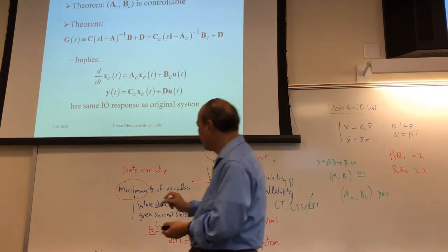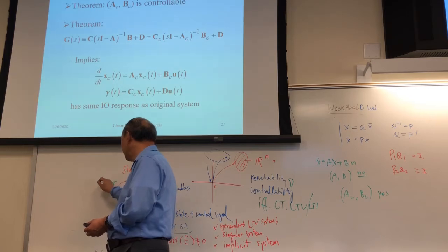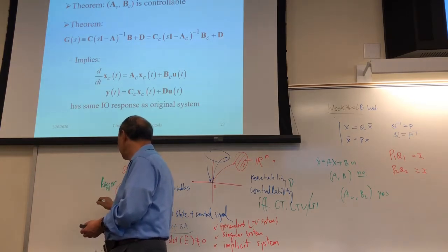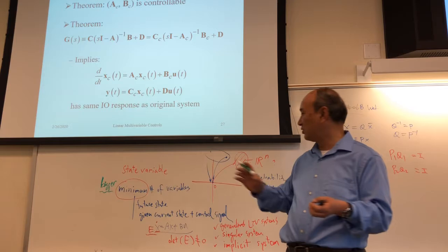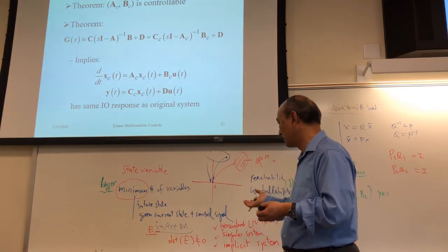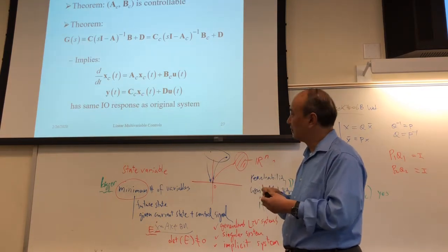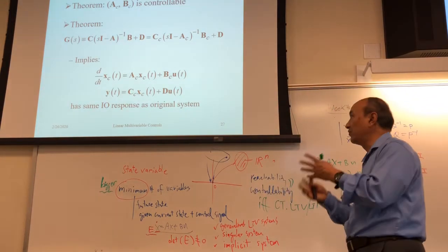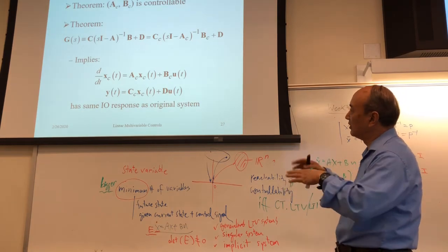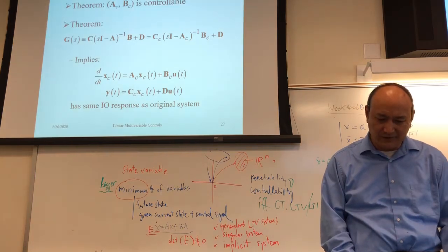While the original bigger system, the reason you had that kind of bigger system is you didn't use the minimum number of states to do this state space development. That leaves you with work to further refine it into two parts, controllable and uncontrollable parts. This kind of decomposition is unique up to a basis change.